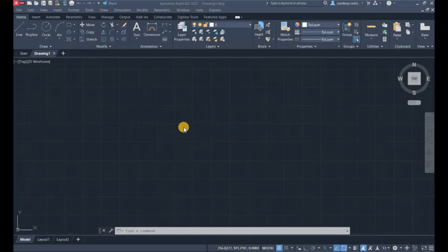So if I were to draw a cylinder in AutoCAD in 3D, I'll draw that particular circle in the XY plane, and then I will give it a depth. This part here, giving it a depth, the term is called extrusion or extrude. So it's like push and pull. From a circle you are pushing or pulling out to get your cylinder. In other words, that push or pull is referred to as extrude.